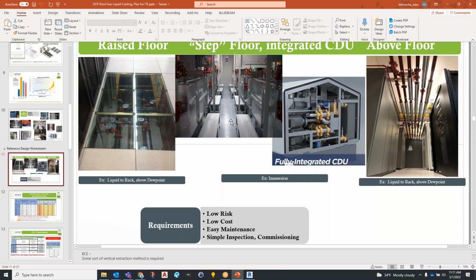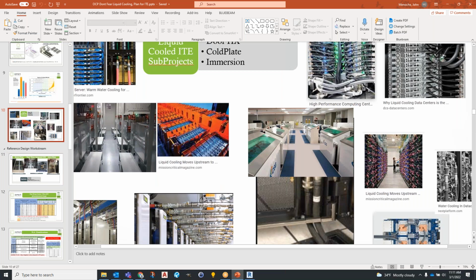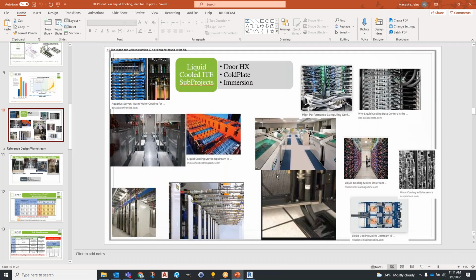My thinking behind that is it's been common practice for a while for us to run structured cabling infrastructure over the top of the racks when we deal with conventional racks. If we say we can do, say, 2.5 meters of overhead clearance, and you have an immersion solution, for example, that needs 2.6 meters of overhead clearance, and there's cable tray over the top, it simply doesn't work. So we need to understand what those requirements are from the community today.